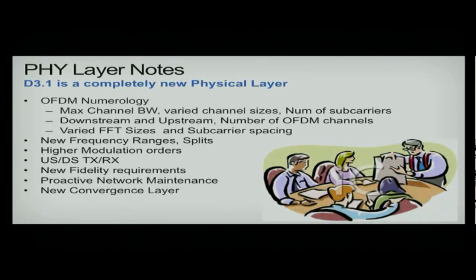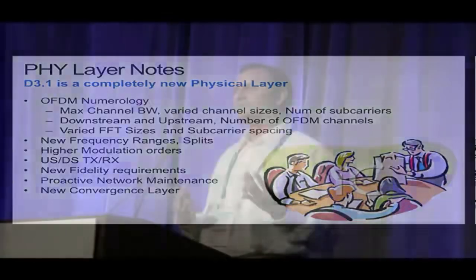And what kind of FEC we would support. For DOCSIS 3.1, the FEC looks very similar to the DVB-S2 FEC on the downstream, and on the upstream it's a new LDPC FEC. Then there are fidelity requirements and proactive network maintenance requirements, which started in DOCSIS 3.0. A lot of those requirements are making their way into DOCSIS 3.1 as well.